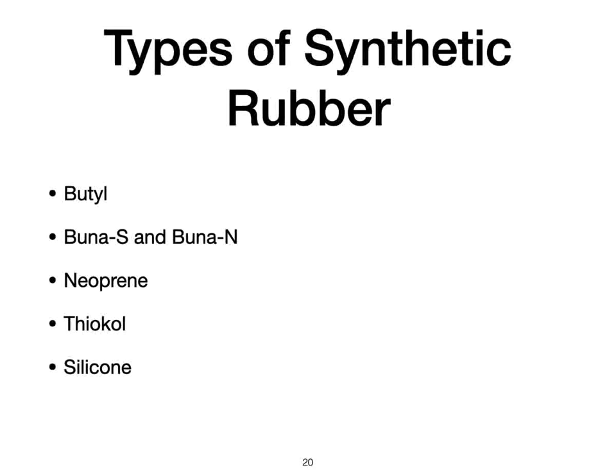There are different types of synthetic rubber. The major ones are butyl, buna, neoprene, thiokol, and silicone. Butyl is a synthetic hydrocarbon rubber that is especially resistant to gas permeation. It is also resilient in exposure to extreme cold and extreme heat. It is most suitable for use in materials that come in contact with gases, ketones, acetones, and hydraulic fluids.